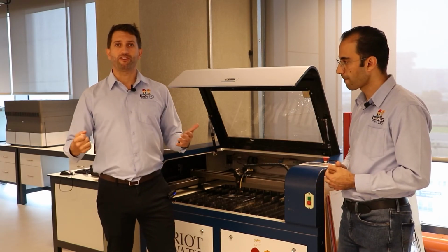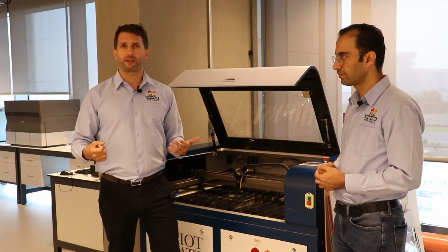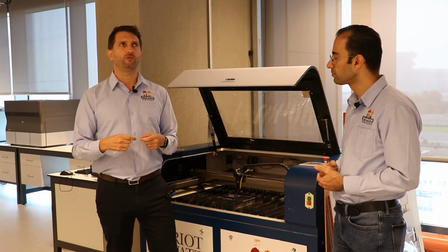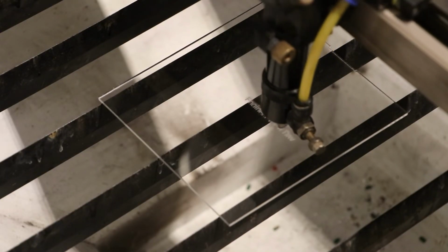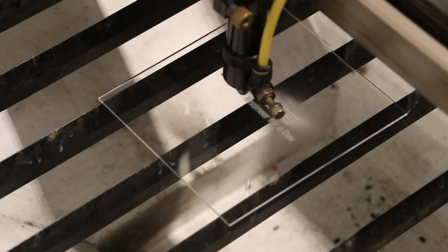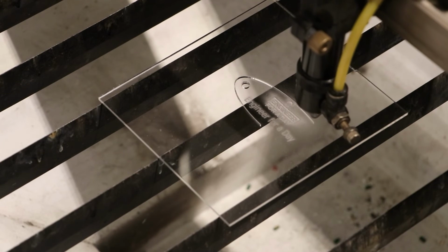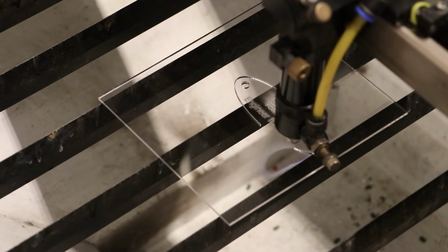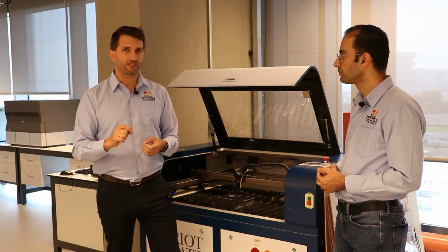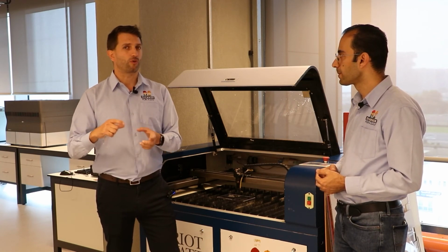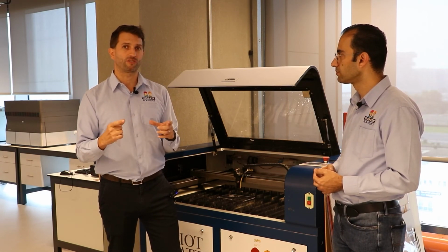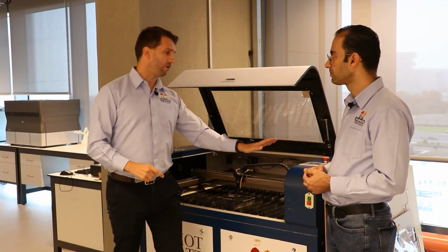Okay, so you've now made your design and you've done that in a drawing package. We'd consider that CAD, a computer-aided design. And then you took one step forward and you defined the toolpath. You essentially said what lines on your drawing are going to be cut, so high-powered laser at a slow speed, and what lines or etches on your drawing are going to be scratched in or etched into that surface or engraved. And that would be a laser moving much faster and perhaps at lower intensity. So going from the drawing to the instructions, those computer-aided manufacture instructions, those then get uploaded to our laser cutter here.